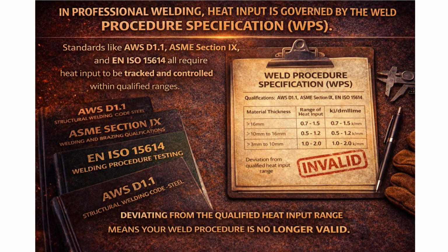In professional welding, heat input is governed by the Welding Procedure Specification, or WPS. Standards like AWS D1.1, ASME Section IX, and EN ISO 15614 all require heat input to be tracked and controlled within qualified ranges. Deviating from the qualified heat input range means your weld procedure is no longer valid.